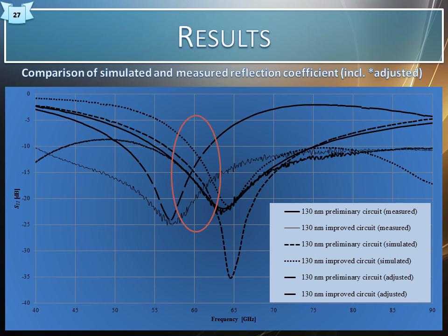The results confirmed that changes in inductance values occurred, large with respect to the changes in the capacitance values, which could be assumed reasonable error between simulated and real-world parasitic parameters within the circuits as a result of the ground plane acting as an inductor due to its geometry. Comparing this theory with the values obtained in the adjusted circuit, which suggested enlarged inductance values, was consistent.